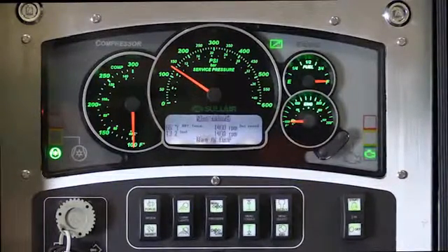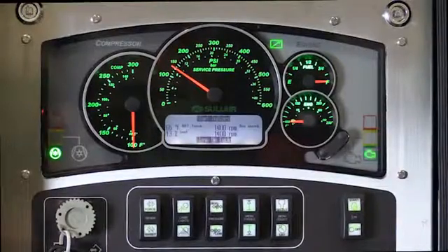How long the compressor is in the warm-up mode depends on 3 things: minimum warm-up time, maximum warm-up time, and engine coolant temperature. All 3 parameters are programmed into the C-Pro, and they can vary depending on engine model.